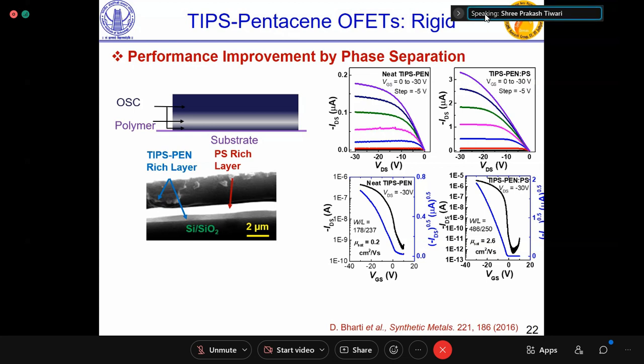So it means oil and water have an interface which they form, and they don't mix up. Similarly, if you do these kind of strategies where you mix dielectric and semiconductor, rather than depositing dielectric or semiconductor one by one, in some cases you just mix it and deposit it, and they automatically form two layers. And in that case, since it is naturally formed, it might give you a better interface, rather than if you deposit one material, wait for some time, and then deposit the second material.